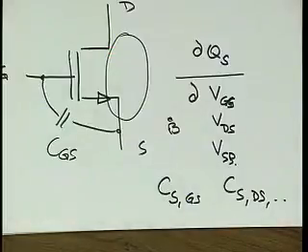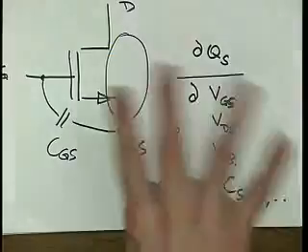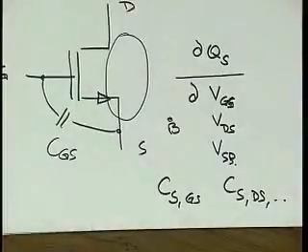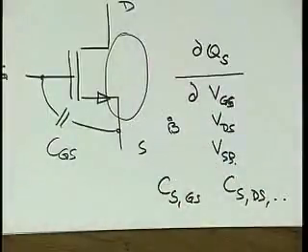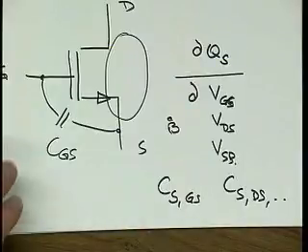So all modern versions, all modern SPICE models, they use these charges. They model the charges, and then if you want to get a capacitance, it calculates these derivatives for you, but you really get 9 per transistor. And none of the 9 really corresponds directly to a simple but unfortunately flawed model. So you always got to be a little bit careful about these capacitors.